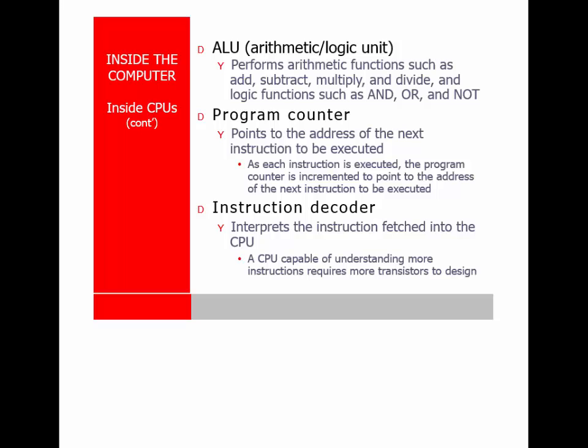I'm going to take a little bit of a sidestep here and talk about two types of processors. We already talked about two types already, and now there's another two types. The two types we're going to be talking about in more detail in this class are the general purpose microprocessors and the microcontrollers. A microcontroller is a processor that has internal to it the memory and the I/O and sometimes analog and things like that. With the microprocessor, all that stuff is outside the chip, and you have to have additional chips.